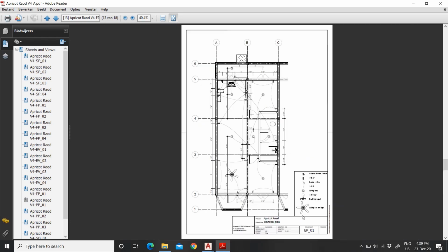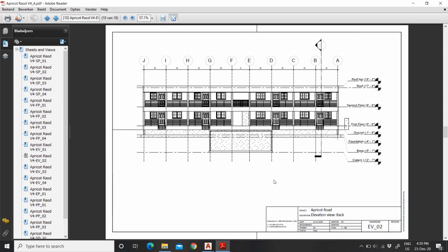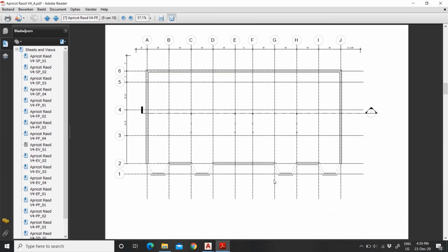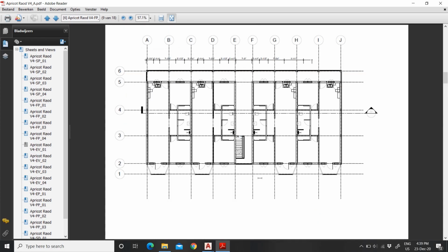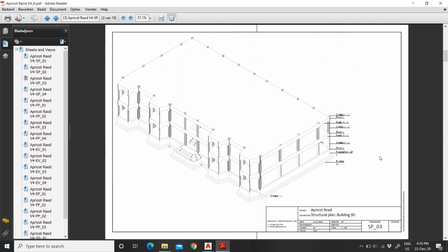and here you can also just add your different floor information to your title block. This is a next title block, by the way, guys, that I had in my template, because this one I did with a different template. So then you just fill in your title block for each and every drawing in your paper space, and you just export it to PDF or whatever you like, or publish it to your printer, all in one go, instead of having to go in Revit and make each and every one of those families just to be able to use dimensions. I found it ridiculously extra, much extra to do.